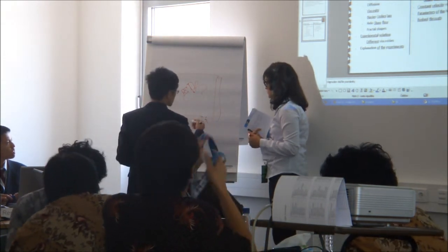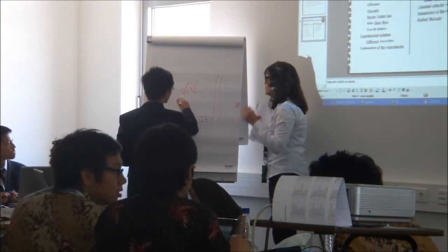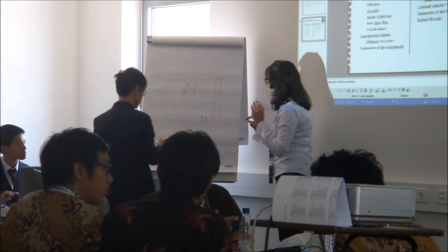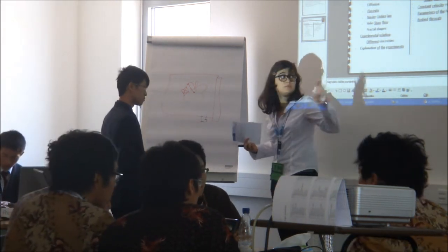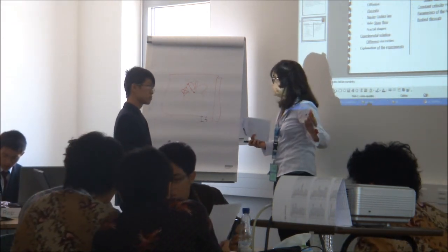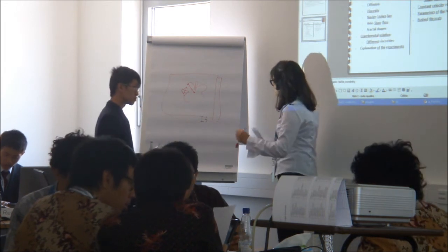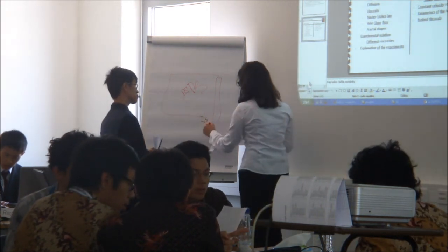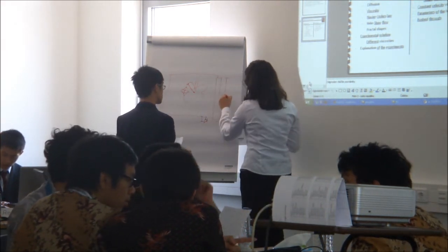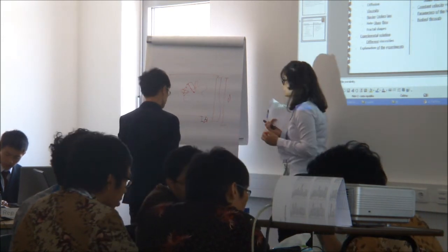So you said that when the distance between the gap is very big, then not very big. We cannot have a very big distance, because we cannot approximate this to a Hele-Shaw flow, because we need this distance h to be much smaller than the length of the plates themselves.